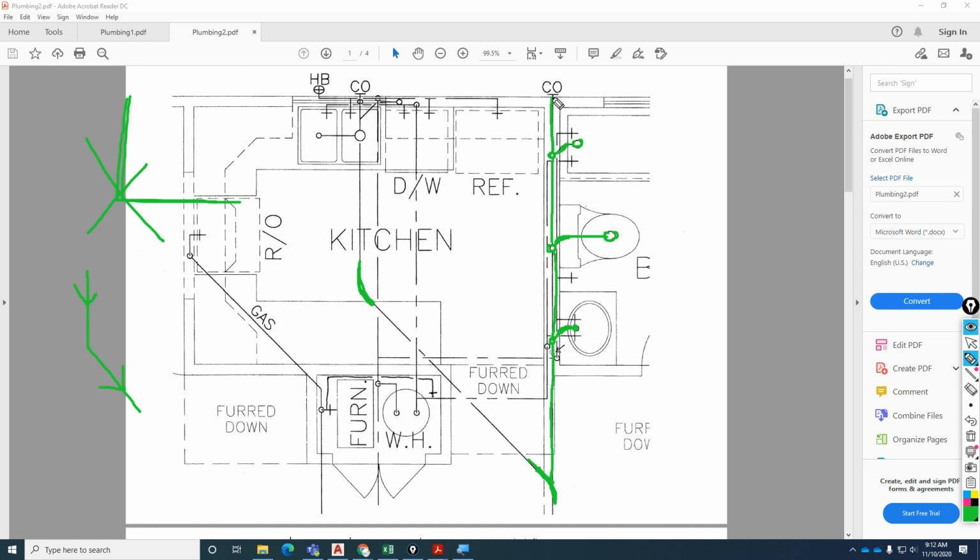Once again, it's not a bad idea to add another clean out at the end of this line. We don't have to do that, but these are the things that make it nicer. If we didn't have this clean out, and it does happen every once in a while, how could they clean a clog that could have happened somewhere in here? Let's say there's a clog in here, and you don't have a clean out back here. What do they have to do? They sometimes have to go through the water closet with that cable system in the restroom, and black stuff comes out and gets all on the floor and starts smelling in there, and the plumber is all sweaty. It's just little things that can make your life a lot easier. That way the sweaty plumber can go in the backyard.